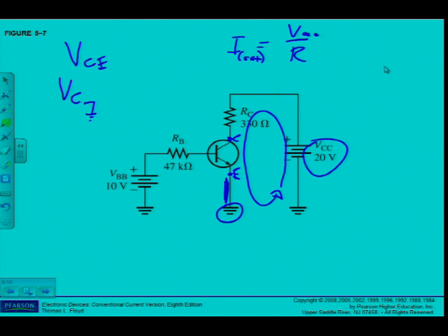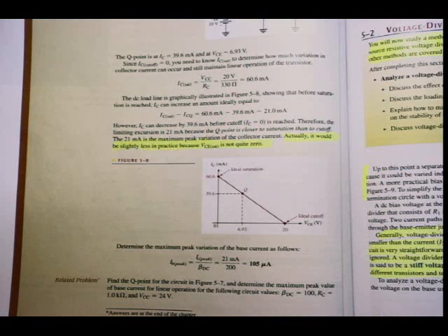I know, those are two C's actually. VCC. And what is the resistance around this circuit? What is the resistance? RC. There is no other resistance in that circuit, né? So maximum current is going to be determined by my supply voltage and the resistances around this series circuit. Simplified a bit, it is not exactly true, but let's stick with it at this stage. Maximum current is then VCC divided by RC. And we get a value of 60.6 milliamperes.